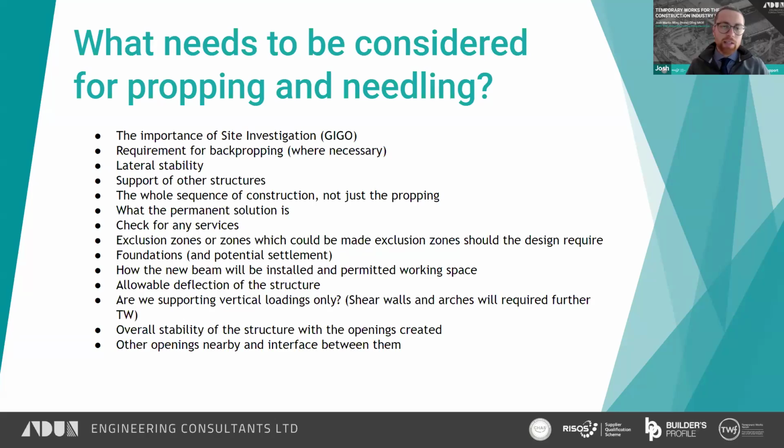We need to understand the constraints and the limits of the structure. So we need to know the allowable deflection on the structure during the works. There will be some movement. Any openings in load-bearing walls will lead to some movement. Often it's just some micro cracking if we've got lots of supports in there. But we need to know what kind of movement limit is permitted and essentially how much is too much movement. The loadings that must be considered, are they all coming from above, or are they point loadings, or are they evenly distributed? And then finally, the overall stability of the structure.